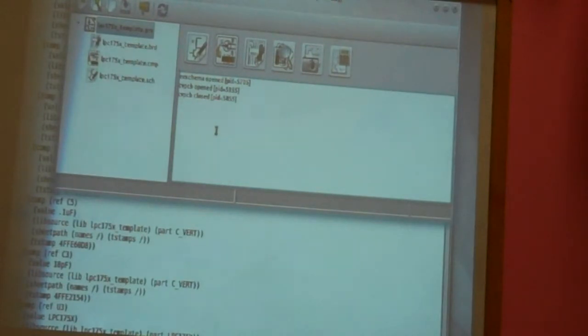But it's key to understand that in KiCad, footprints aren't bound to components until this step. Other editors, other tools, bind the footprint in the schematic editor, but not KiCad. Some people really like it that way, and some people say that's not really the right thing to do. There's discussion.